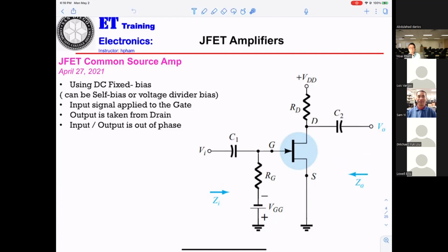And also don't rely on the 50 ohm resistor in the generator, correct? Because that's technically not a DC blocking resistor. No, you're talking about the output of the generator, correct. Yeah, that's for the generator. Normally they're using 50 ohm. But for the circuitry, it depends on the circuit.